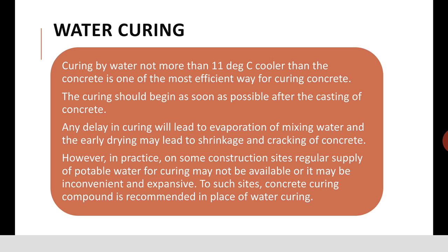Water curing. Curing by water not more than 11 degrees centigrade cooler than the concrete is one of the most efficient ways for the curing of concrete. The curing should begin as soon as possible after the casting of the concrete, meaning after initial set of concrete. Any delay in curing will lead to the evaporation of the mixing water, and the early drying may lead to